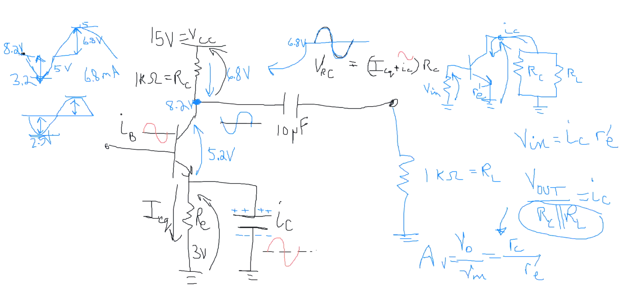You need to know that in the AC mode, you actually have exceeded the limits that were put on you by the DC circuit. This maximum current was VCC over RC, and with RE in there, you would actually make it over RC plus RE. That is no longer a constraint when you have the additional load providing current to you.